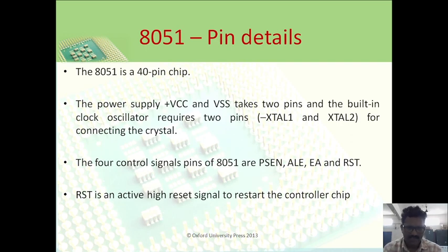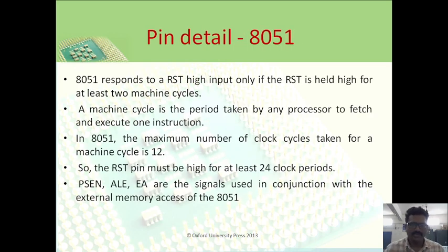RST is an active high reset signal to restart the controller chip. The 8051 responds to a RST high input only if RST is held high for at least 2 machine cycles. A machine cycle is the period taken by a processor to fetch and execute one instruction. In the 8051, the maximum number of clock cycles taken for a machine cycle is 12. So the RST pin must be high for at least 24 clock periods.